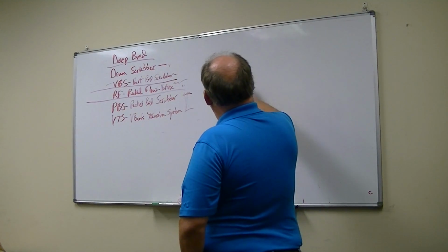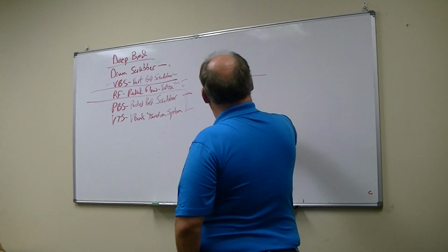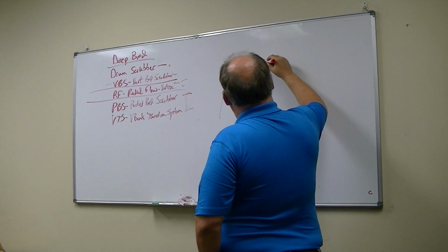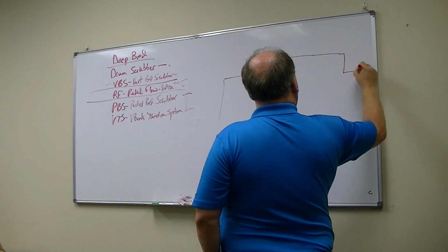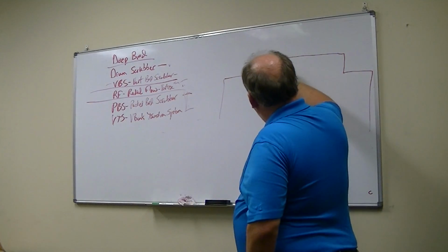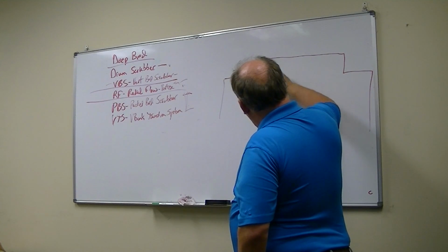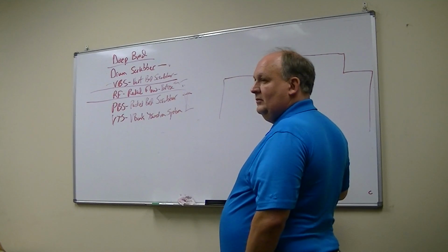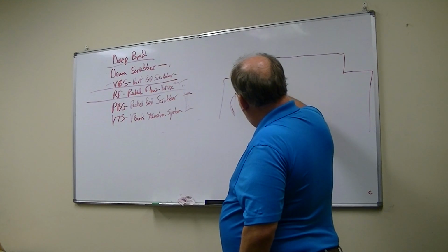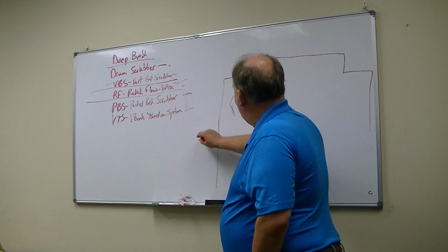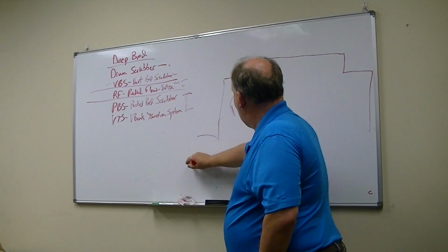Okay, so if the system is like this, he does his little fill chute, not a very high fill chute at all. Okay, but he uses an internal baffle coming down here. Okay, so this is plenum, so before it even gets to the media. Yeah, airflow coming in here.